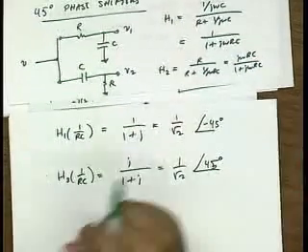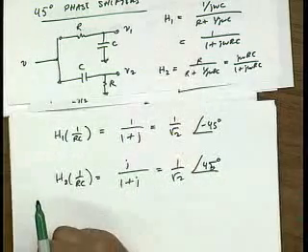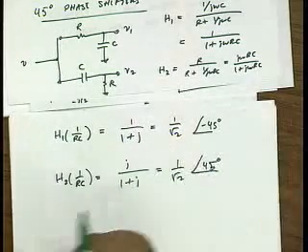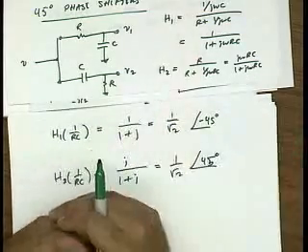That's how you do it at really high frequencies. If you go to really high frequencies, you basically use transmission lines to build phase shifters. And actually, transmission lines are superior because it's a real phase shift, right? It's a real phase delay.